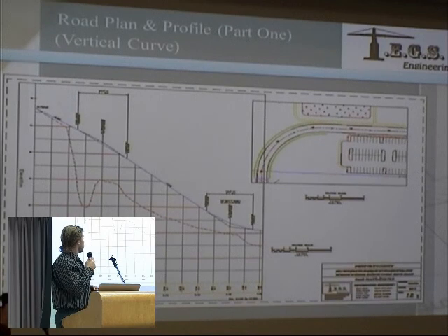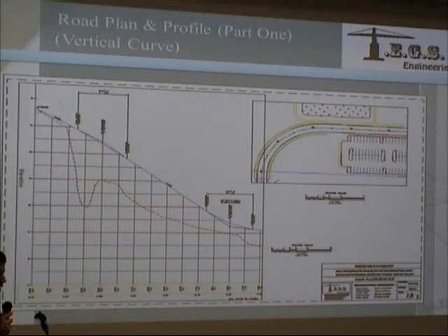Here's the first part of our vertical curve on the site, and up here was where we matched our proposed road to the existing road, and there's an 8% slope over here, meeting the 62-foot elevation down to our restaurant elevation, which is around 22 feet.